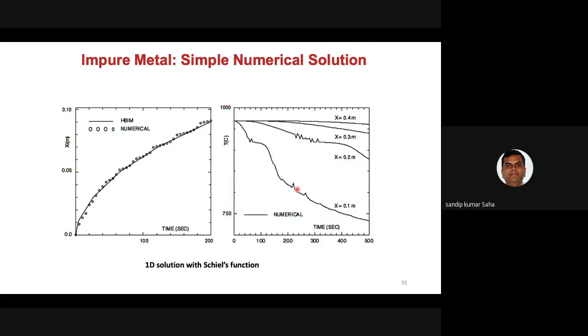Okay, now when you do impure material analysis, for example, right now I'm taking only the example of paraffin, if I want to analyze this. In that case, with paraffin, you don't know the composition. Paraffin is actually a mixture of hydrocarbons. It's not a pure material. Okay, so paraffin is a mixture of hydrocarbons, but you don't know which hydrocarbons are there in what percentage. That's the problem. So if you don't know that percentage, you cannot employ the species equation.